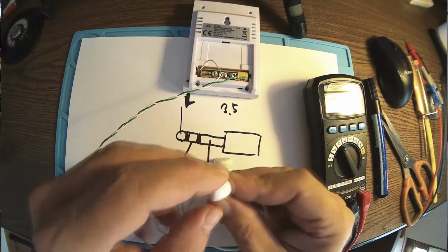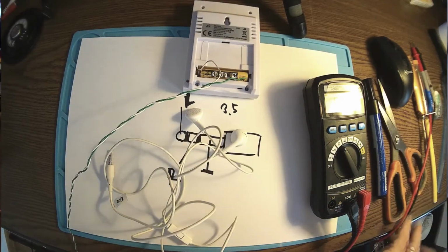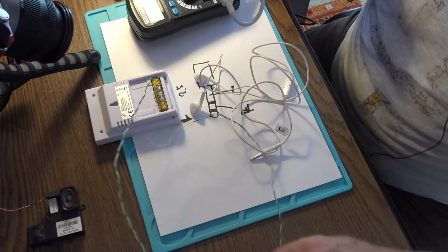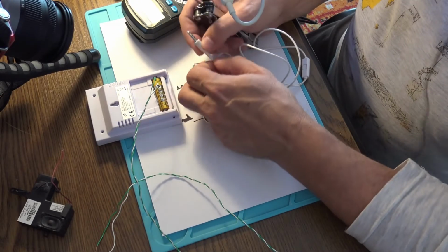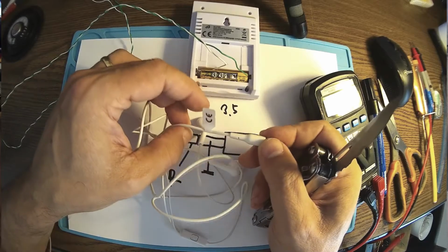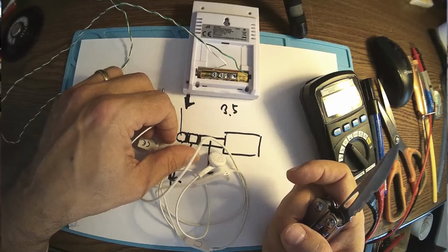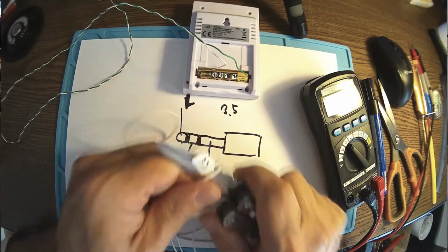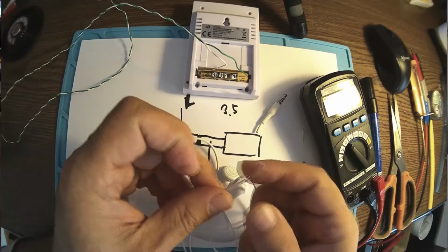Let's imagine that one of the headphones is not working anymore. The first thing we have to do is to check the wire, because in most cases the problem is in the connector. This connector here so many times gets broke. The wire gets broke, and this is a very simple way to do that. But that means destruction. So unfortunately, you have to cut the wire like I did.